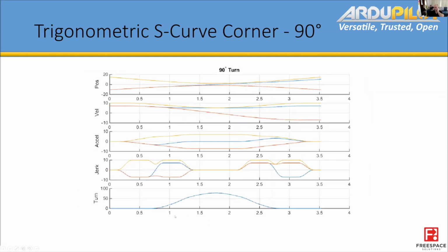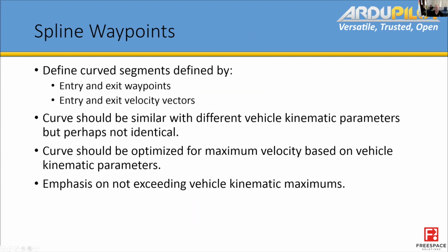And so this is the jerk cell velocity, and as you can see here, we're able to predict ahead of time what our maximum turn rate is. You can see even our turn rate accelerates into the turn, reaches a maximum turn rate, and then decelerates out of the turn. So I'm really happy with the way that manifests itself in the way the aircraft flies around a course. A dramatic improvement for our linear waypoints.